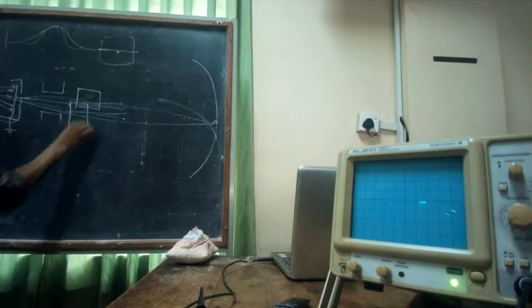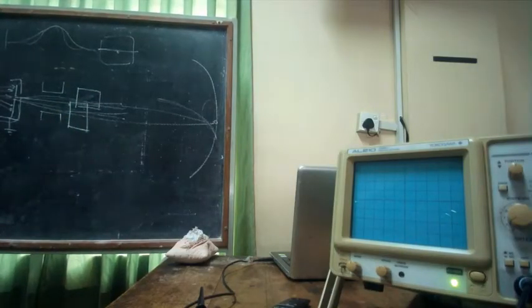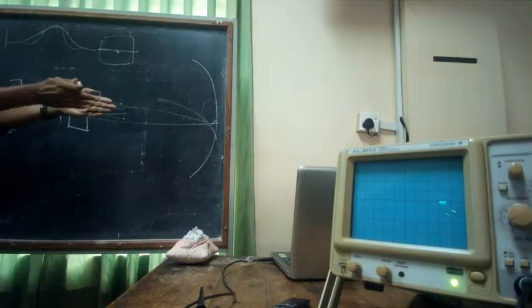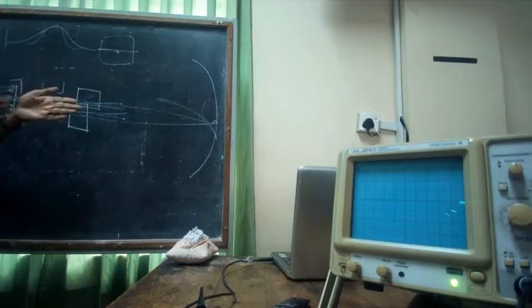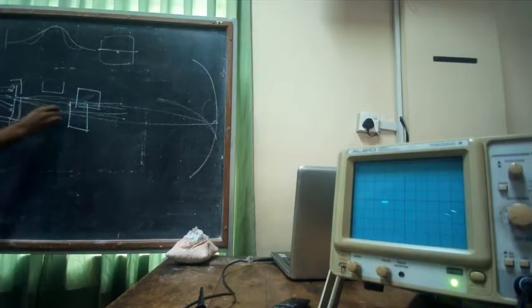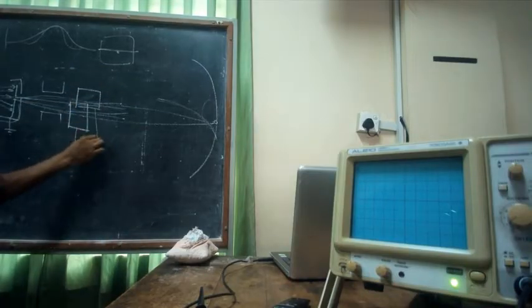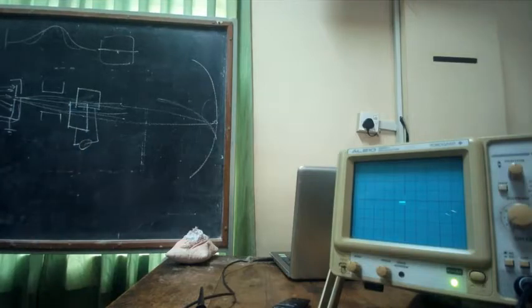These are electrodes that are like this, right? So they are parallel electrodes, and the electron beam goes past that. Okay. So by applying a voltage between this and that, you can control where it hits on the screen, whether it is here or here, right?